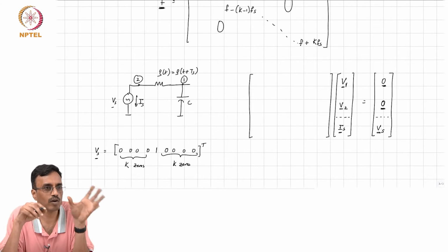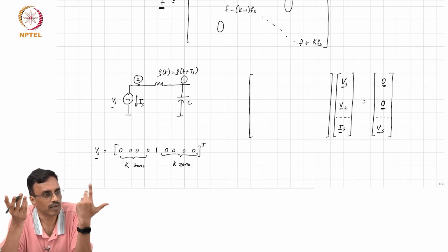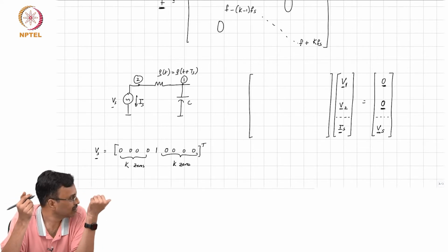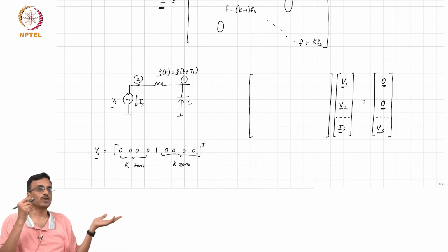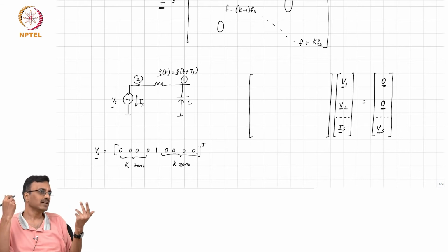All that you are doing is now replace the MNA stamp of a time invariant element with that of a time varying one, right? And all these equations are just a shortcut way of writing KCL and KVL at every frequency. At each frequency, KCL and KVL must be satisfied.